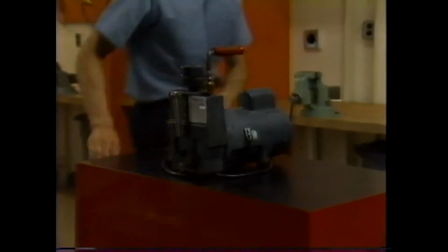A vacuum pump is used to evacuate or remove air and moisture from the system. The vacuum pump does this by using the same principle we saw earlier. Low pressure equals a low boiling point. It creates a vacuum in the system, usually expressed as inches of mercury.